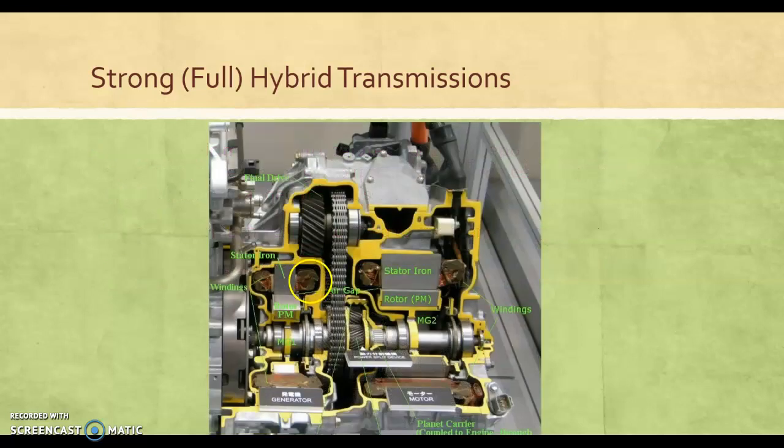Here's a cutaway of a Toyota transaxle, and you can see right here that MG1, where my mouse is, is the cutaway of that permanent magnet rotor. And then here is the stator of MG1 with that iron lamina right here to cut down eddy currents and enhance electromagnetism. Over here is MG2 and then MG2 rotor. Look at the gap, very, very small gap right there. Okay, so be very cautious if you're moving these permanent magnet rotors and use the appropriate tool, because your finger will become that thick if you try to put it in by hand and you're not careful. So be careful.